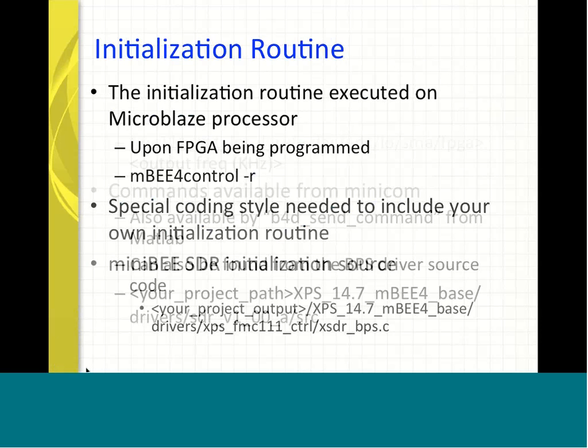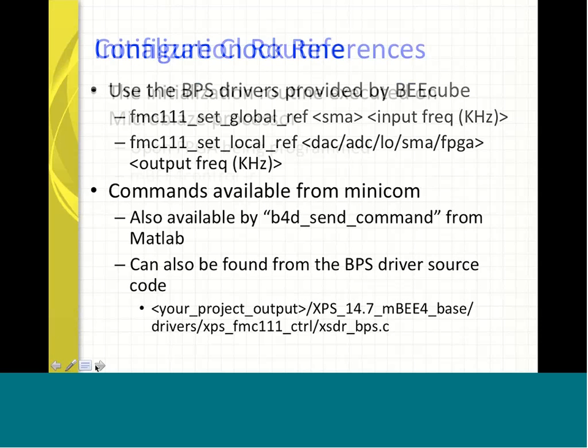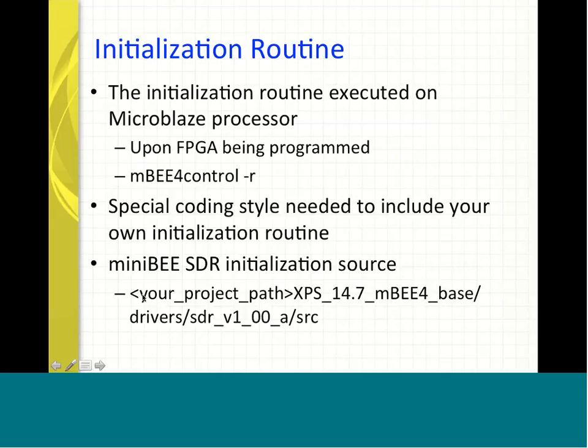Another question I got, because I want to go through the discussion on the drivers, so I want to cover this slide as well. Some of the initialization routine executed on the MicroBlaze processor is automatically run when you program the FPGA, or when you run MB with Control-R to reset the FPGA.